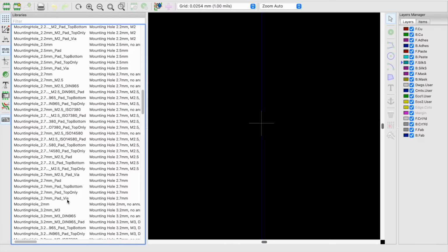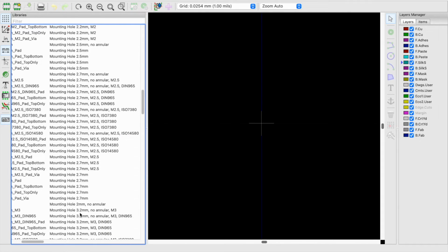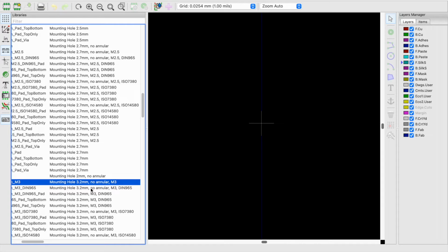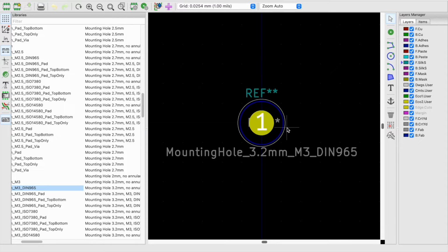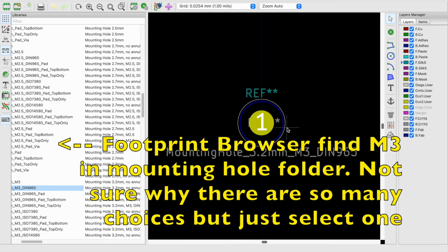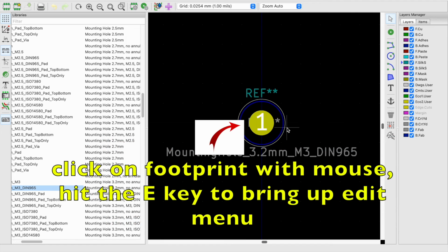So I am partial to the sort of elongated oval shaped Eurorack mounting holes. So that's what I'm going to show you how to create right here, and then I can briefly show you how to do just the regular old round hole. Luckily, it's right there. You can see it on the screen there. The Eurorack mounting screws are typically like M3 screws, so you can use just simply an M3 mounting hole in PCBnew, and that should work just fine. Sometimes, like I said earlier, I might go in and edit it and increase the size a little bit, just maybe by 1/10 of a millimeter or so, just to give the PCB manufacturer some leeway.